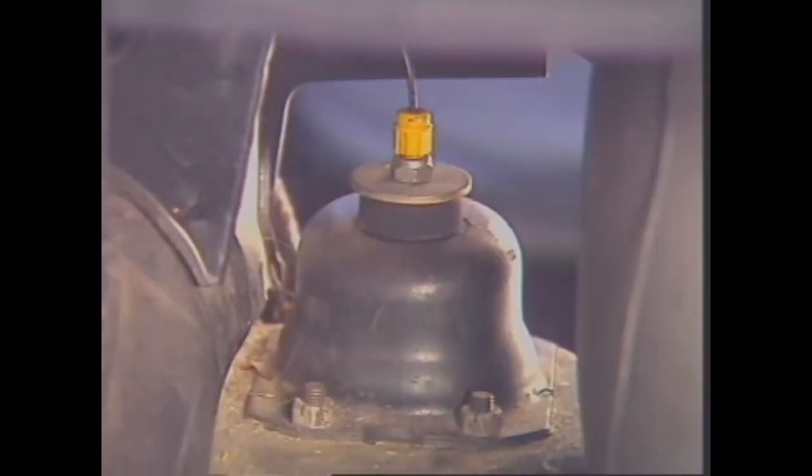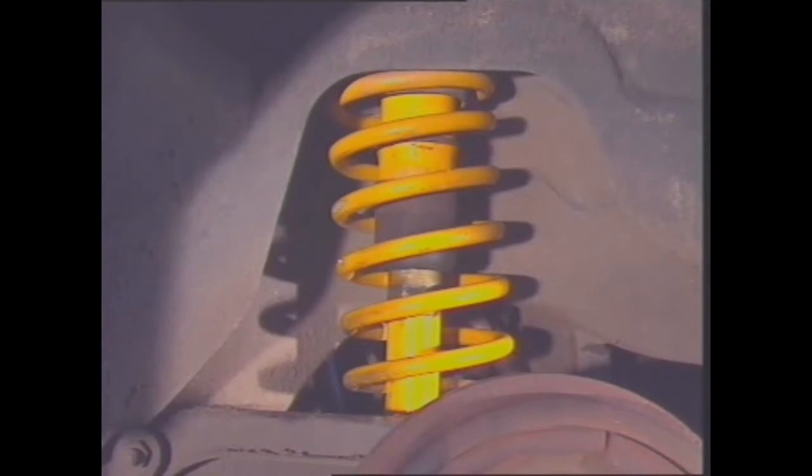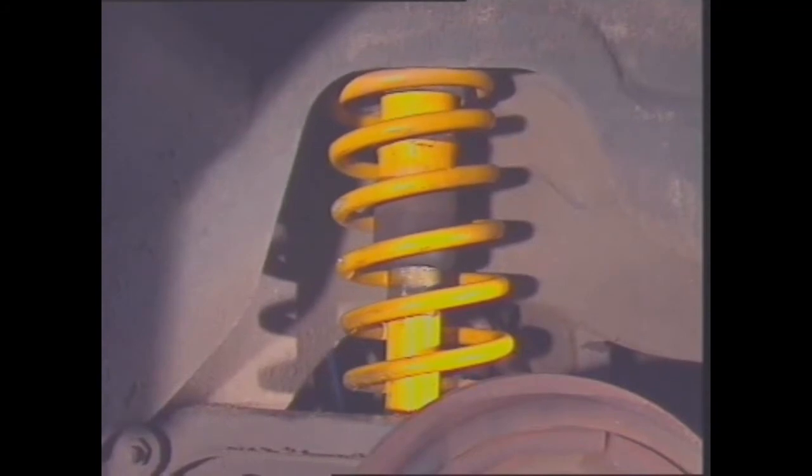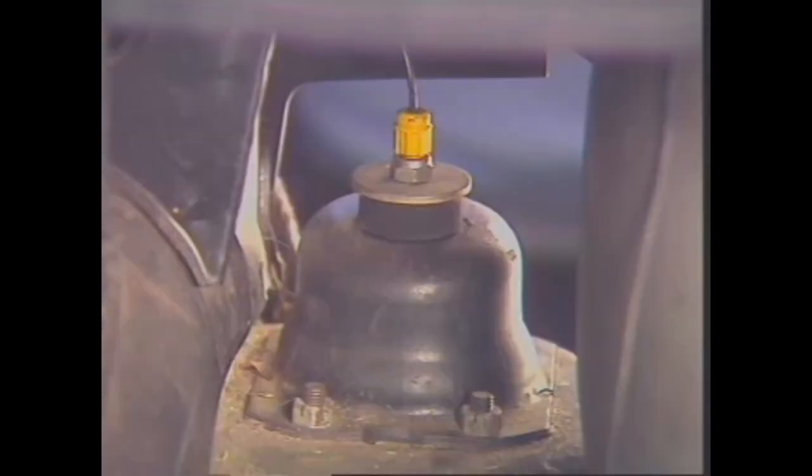The rubber air cylinder is connected to a filling valve by a flexible plastic hose. Air from a tire pump or a hand unit forces more air into the rubber cylinder, allowing the suspension to support more weight. The maximum air pressure setting must not be exceeded, as this can damage the shock absorber and its mounting points on the vehicle frame.